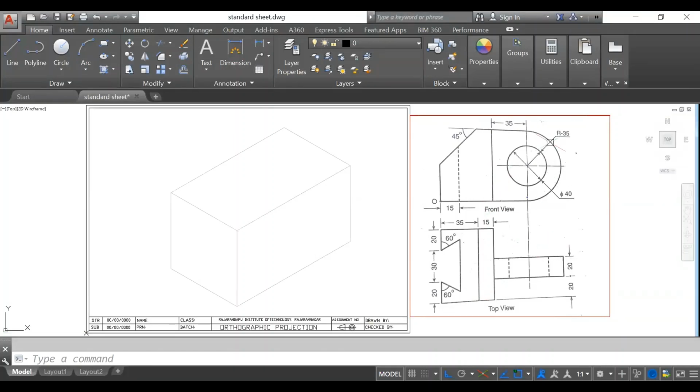If you observe the front view, while observing the diagram you have to look into both views. So I will divide this diagram into two parts. One part is from this line to this side, and one part from this to this line. So how is it looking in the top view? It is looking in the top view only as a rectangle having a thickness equal to 20 mm, not from here to here. So this surface is available in this region only. Even though it is not exactly at the middle, it is 20 mm from this side. So 20 mm from this side, one rectangle is there in the top view, and that shape is circular. So a half circle is there and a full circle is there.